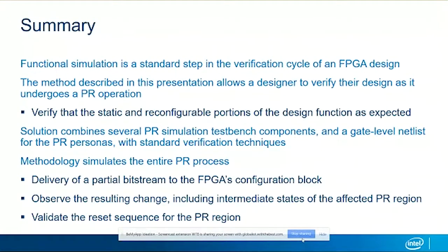You can detect problems before you go to the board, so that when you're at the board, you're now looking at things from a system level, making sure that your whole system works the way you expected, as opposed to having to try and debug the configuration operation. This methodology that we've described combines a mixture of tech map netlists, so mapping to the physical implementation on the FPGA, together with behavioral simulation in a System Verilog simulation environment that is UVM compatible.